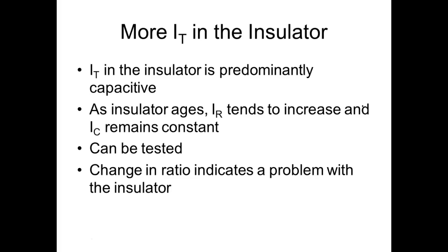We've got a meter where we can check the resistance of the insulator. We call it a megohmmeter. You ever heard of one of those things? What it does, it puts out extremely high voltage, because a regular meter will not check the resistance of an insulator. We'll look at that later.